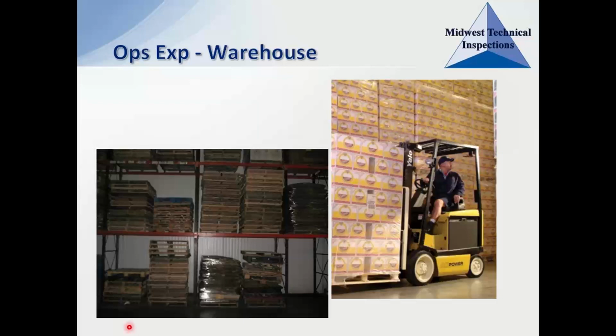So identifying the materials that are being stored. Here we have a bunch of wood pallets, so that's going to be really increasing the fire load inside of the structure. So we want to make sure that we're identifying that so that we can see if they have the proper sprinkler protection for that. And then again, looking at the industrial trucks.